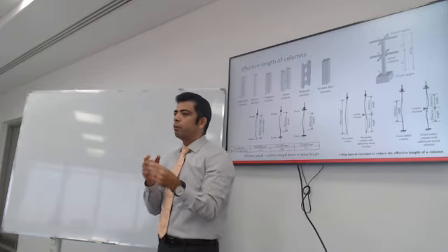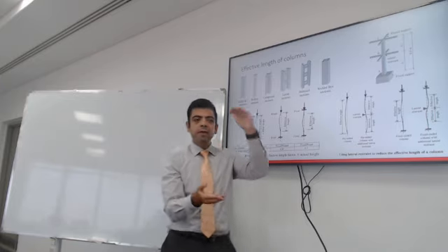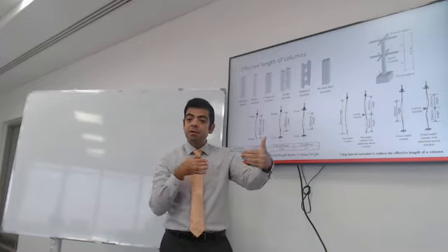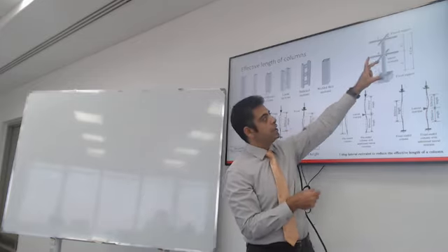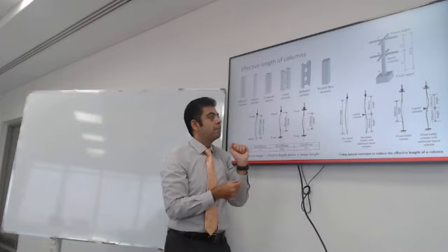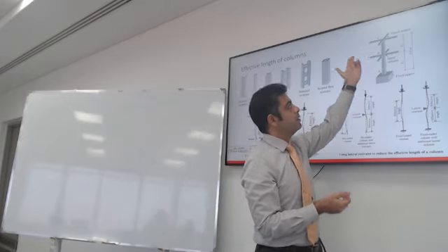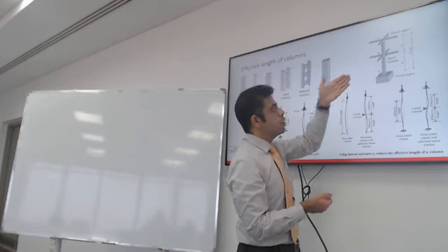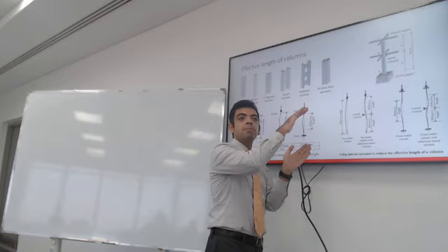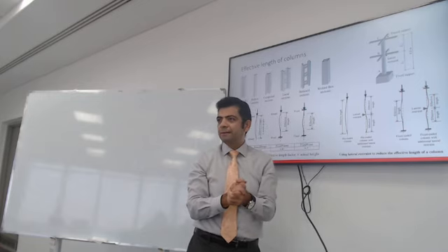Okay? So now we're getting very close to what I expect you to do when you design a column. First, figure out the actual length of the column. Second question, are there any beams framing into the column that will change the effective length? To make things more interesting, you can have beams going in the x direction with no beams in the z or y direction. That means it has a buckling length in x different than the buckling length in y. Does that make sense? Yes.